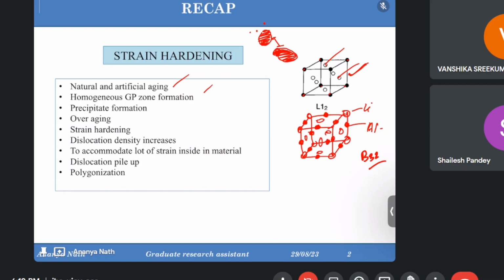So let's see what are the other topics. Before that, there was nomenclature for the cold working strengthening as well. If it's as fabricated, nothing is applied, we use the nomenclature F. If it's annealed and recrystallized, it's O. Then if we have done strain hardening, it's like H1, but under H1 also there are H12, 14, 16, 18.